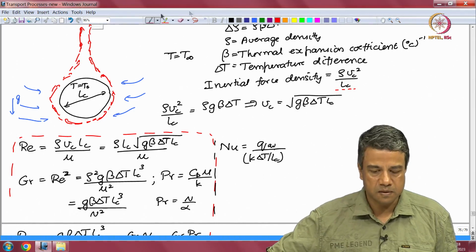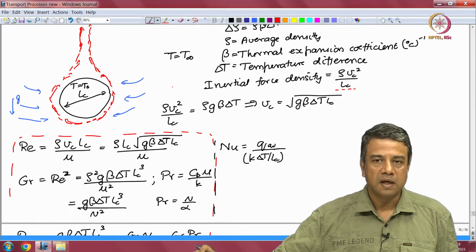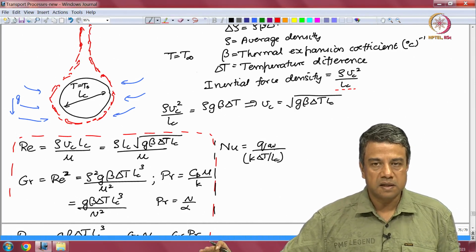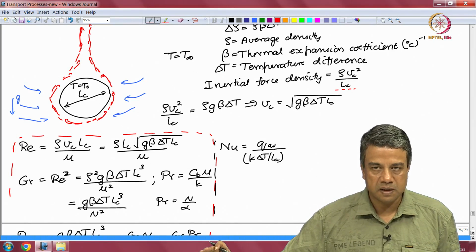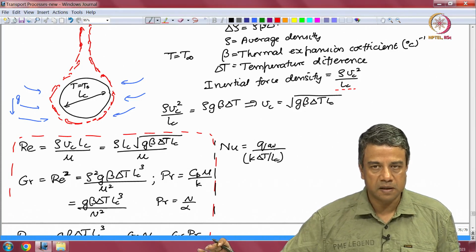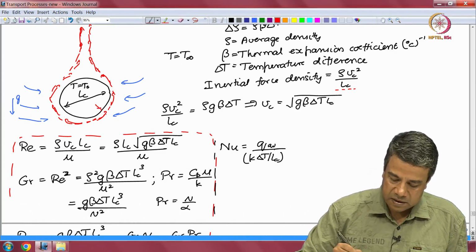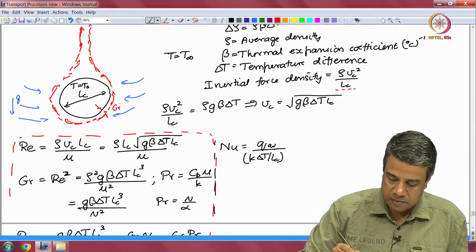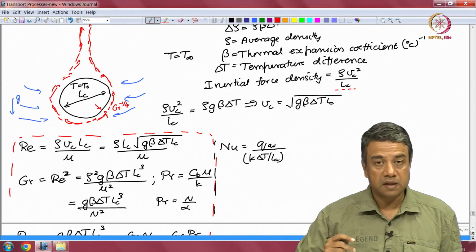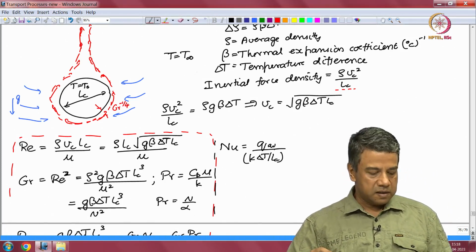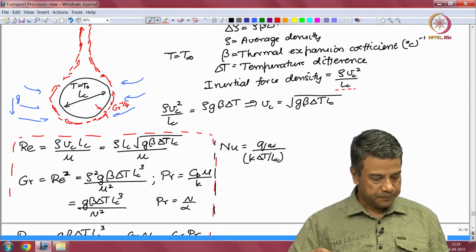So, this assumes that at high Reynolds number, any heat that is being generated by the particle immediately gets swept downstream, so that the temperature disturbance due to the particle is restricted to a thin region close to the surface, and the thickness of this region goes as Grashof number power minus 1/4, in the limit where the Grashof number is large or where convection is much larger than diffusion. Okay.